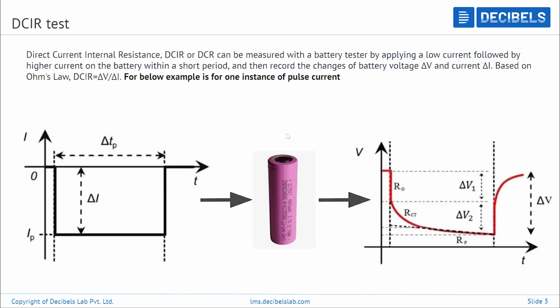So about DCIR. It is nothing but the DC current which we use to capture the cell behavior. There are different approaches; different profiles of DC current can be put into or taken out of the cell, so that you will have different voltage profiles. Whatever voltage profile we get, we extract the required parameters from it. Parameters are nothing but your electrical elements, with which you can construct your equivalent circuit model.